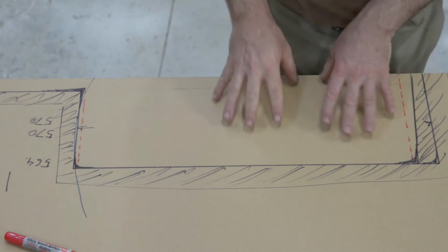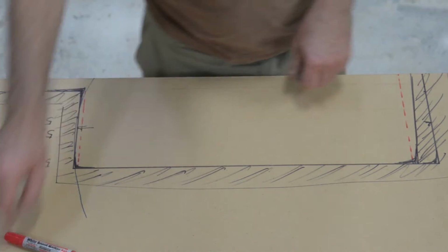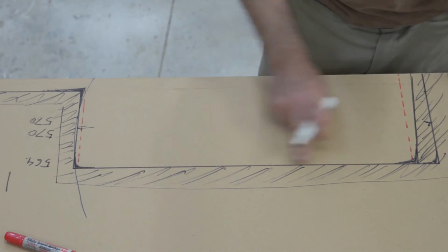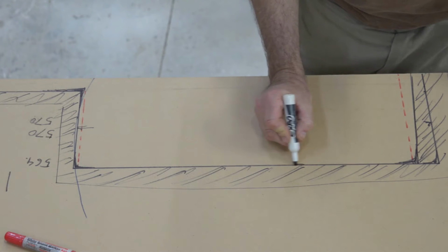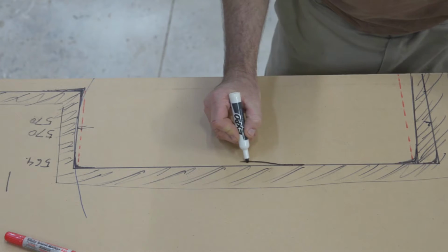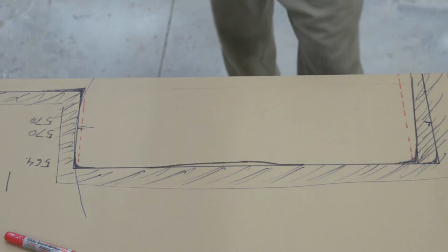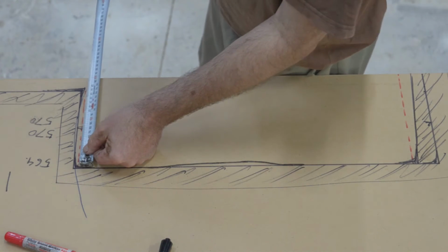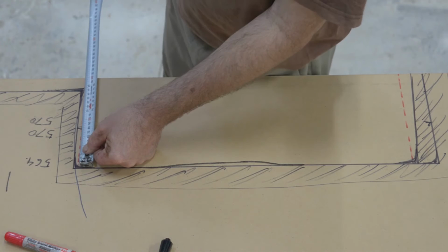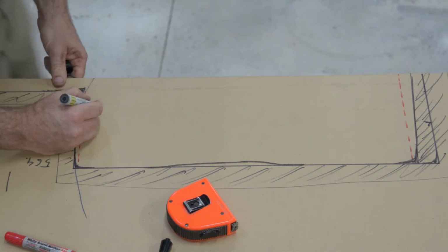Not only that, when we have a square space, we might have a hump or a hollow in the wall. So this wall may not be as straight as I marked it initially here. There might actually be a lump, maybe a crooked stud in there, or just variations that happen on a building site. So we measure the depth over here. I think, oh yeah, we've got 177 millimetres over here. So depth here was 177 possible.